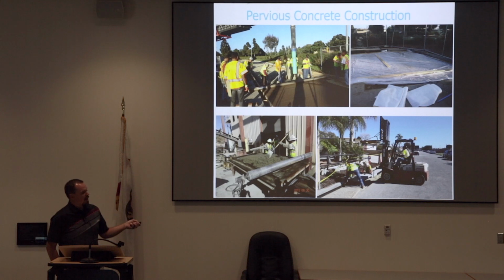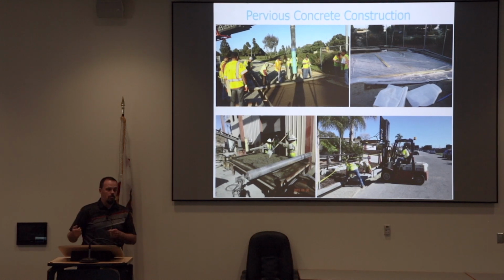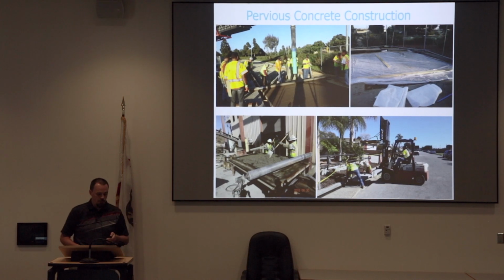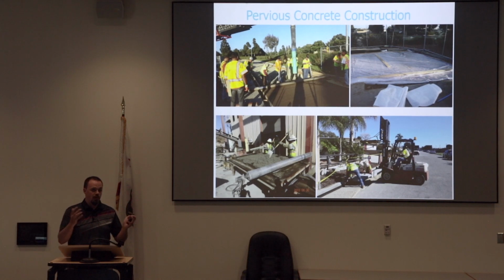This is one reason we put them in, is they have lifting rings in them. If they ever get to the point where they're fully sediment impacted and they're no longer infiltrating, we can actually put the rings in there, lift them out, turn them over, pressure wash the bottoms, clean them all out, put them back in. So it's a way of saving material costs long term as well. With the poured in place, you simply have to demo and replace it, and that can be very expensive.